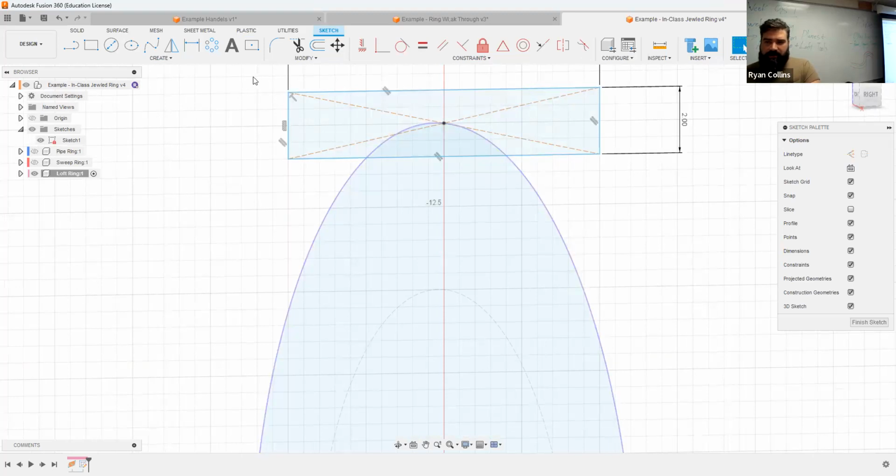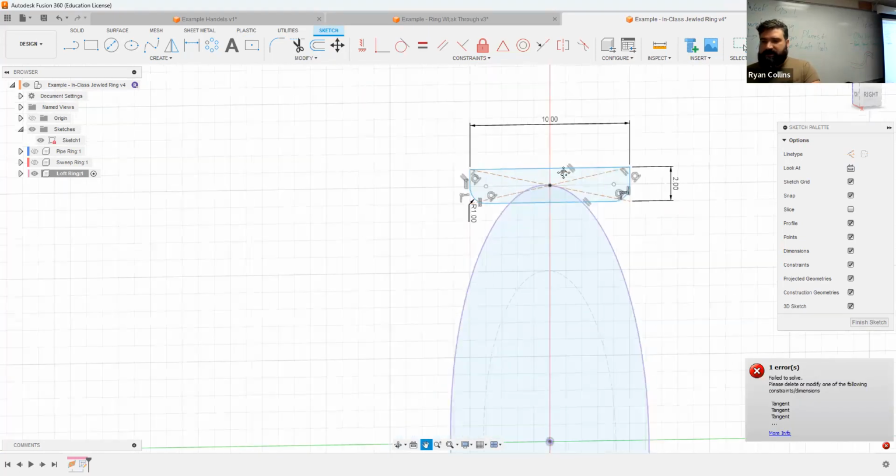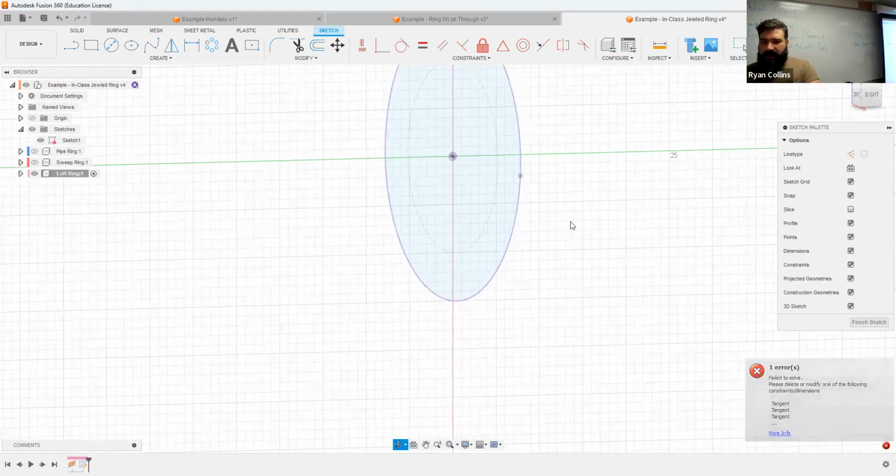All right. Now we do want to make this a little bit curved, so this isn't wildly out of the range. Or let's leave the top. Yeah, let's leave the top flat. So I'm just going to put a couple of fillets here. Yeah, sure, 1 millimeter. Don't hit enter and select the other ones, and it'll link them all. There you go. Now I hit enter. All good. And because they're linked, if I want to go back and change that, instead of 1, double click on the dimension, say 2 millimeter fillet. Now it changes both of them. Neato.